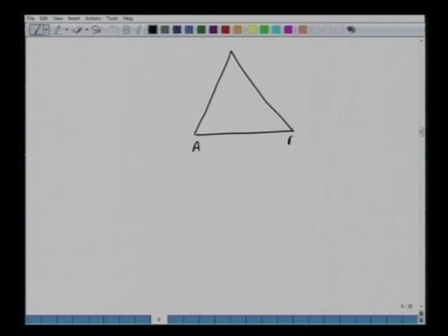A, B, and here you have C. So let's say this is a phase diagram. You have certain tie lines like this, extract, and let's say this is your raffinate. So we have XR and we have this XE or YE. Generally for extract you use Y nomenclature. Here you have XM. Okay, one can also take projections.